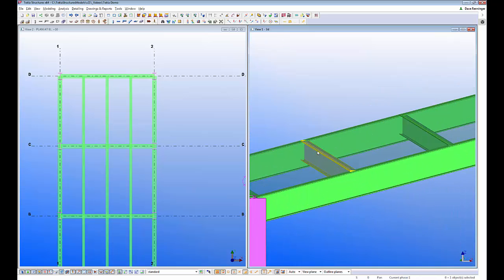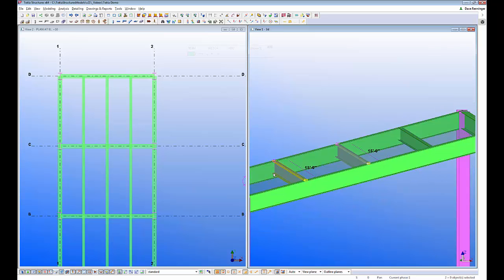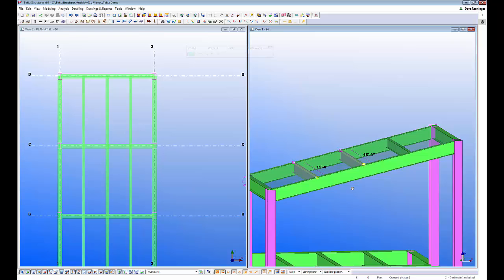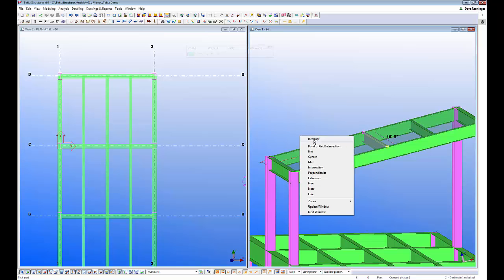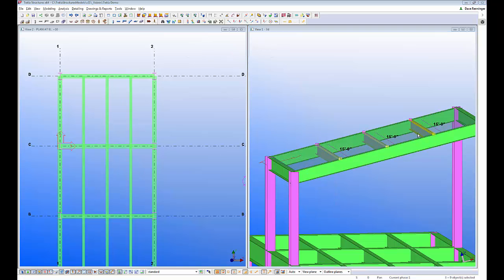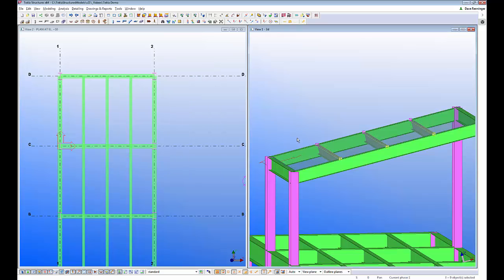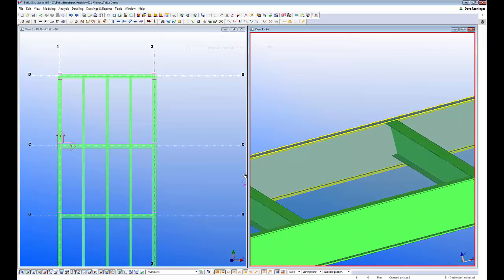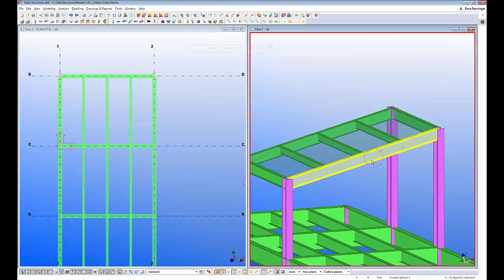All right. But as you can also tell, all these infill beams, even though they followed the roof slope, the rotation stayed true vertical to our z-axis. So again, really easy to modify this as well. I'm just going to come through here and change my work plane first to match that sloping member. Now if I get the properties of these beams, we'll notice that this rotation is set to almost 14 degrees. So if I change this rotation back to 0, now it's that easy to modify all that infill steel to follow the slope of the roof.